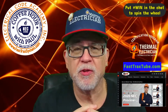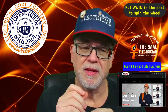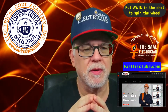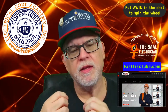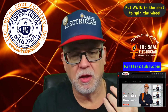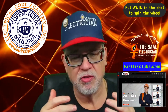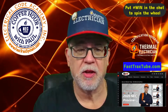But really, we're looking for those hidden things. Sometimes a poor connection, it doesn't have to be a massive load on a poor connection for it to be generating I squared R heat. That can be detected by thermal camera if you know what you're looking for. But we also will get into in our program, we wanted to develop something for electricians to be able to offer as a service, standalone, but also as an add-on service for electricians that are out there doing service calls and they're like, look, would you like us to do a thermal inspection, some key components, and look for any potential issues that may be down the road?